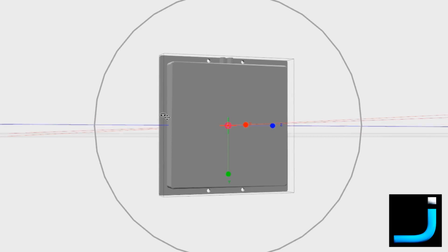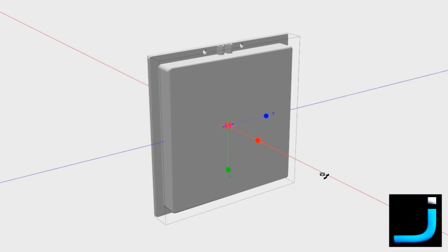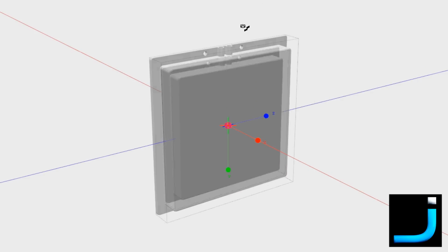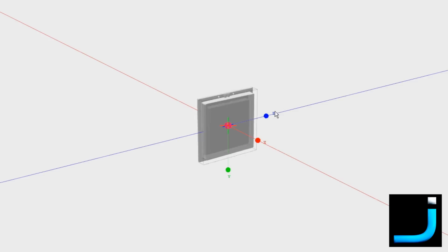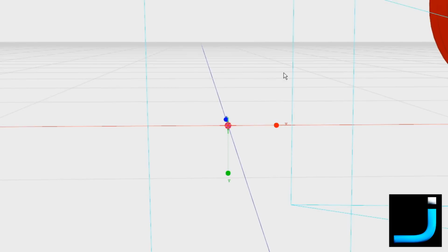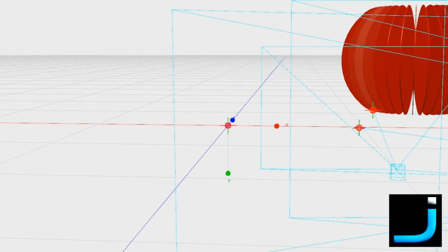This is a diversity antenna, which is 11 dB, so it's 11 decibel gain versus the 2 decibel for the rubber ducky. Now you'll notice they have two cables coming out of the diversity antenna, because it's actually got 2 antennas built inside rather than 1. So this is a flat patch, 11 decibel gain. Let's have a look at the pattern for that.